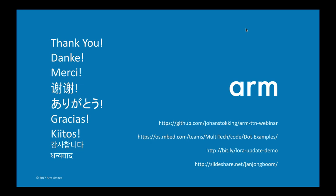Awesome, thank you. Is LoRa suitable for firmware updates for small embedded devices? I think this speaks a bit to Mbed. Yeah, this is actually a really good question. In general, with LoRaWAN the issue is indeed bandwidth. There are different challenges that we see at the same time when it comes to firmware updates. Firmware updates are of course very downlink intensive, so you need to send quite a lot of data back to the end devices.